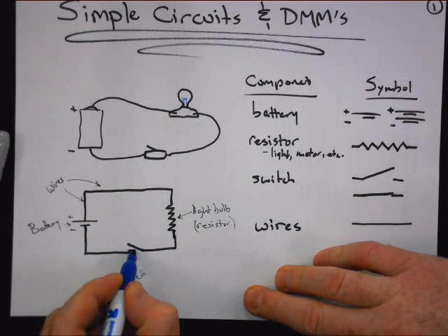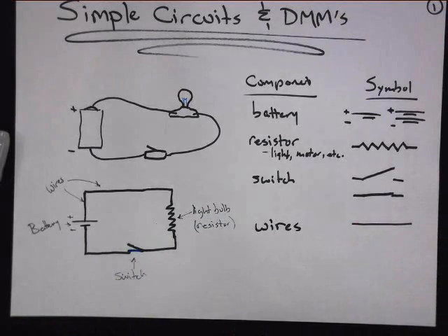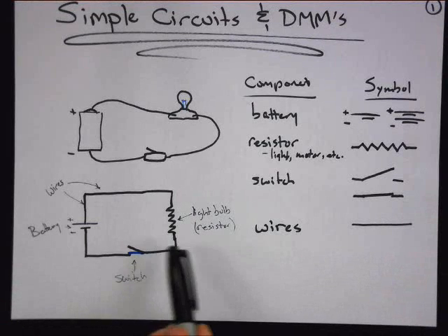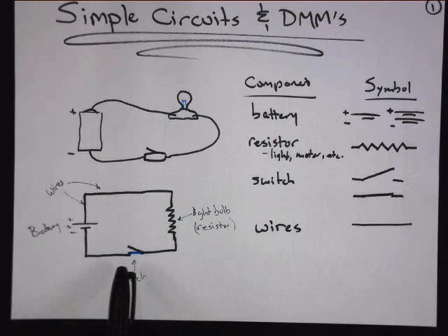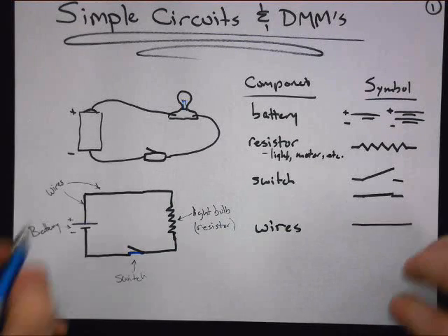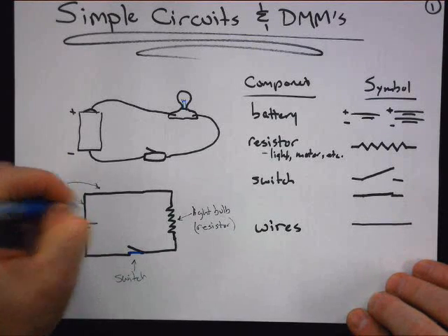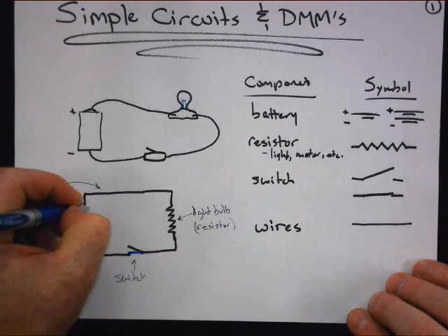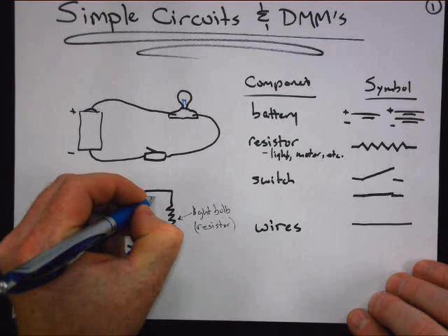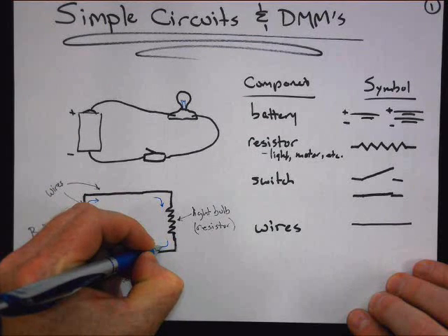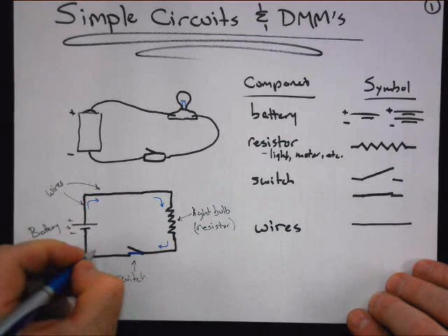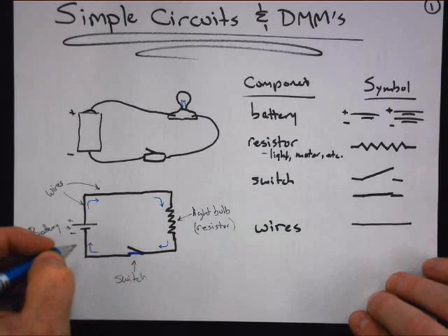So from there, we're touching, right? And so now we're going to get the light bulb to turn on. So now the switch is closed. We have this closed circuit, this complete pathway. And so the current, which way is the current going to flow? Right, so let me draw some arrows for the current. Let me go skinny marker, not the black one. Let me go the blue. I'll show the current with the blue. Current will flow out of the positive end of the battery, through the wires, this, and through the switch, and back to the battery.